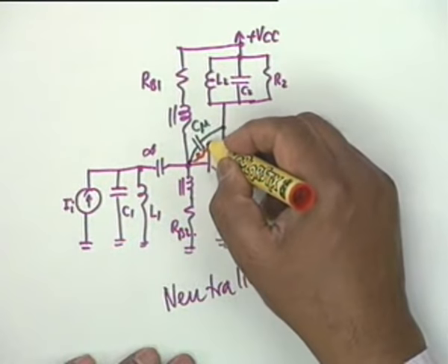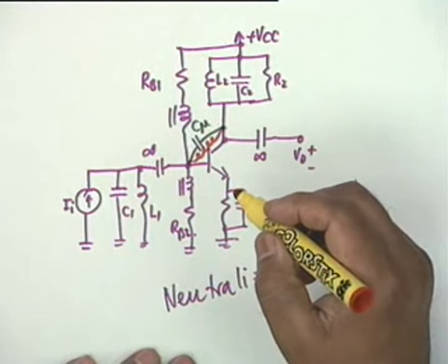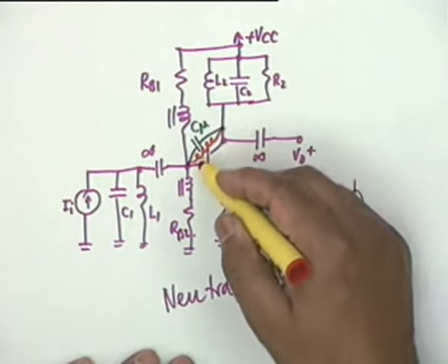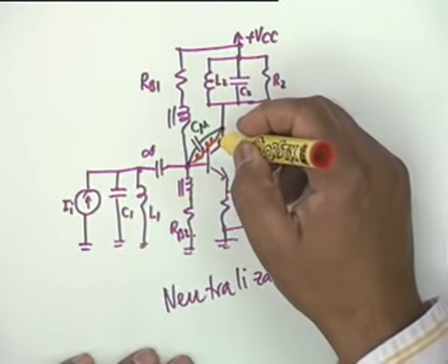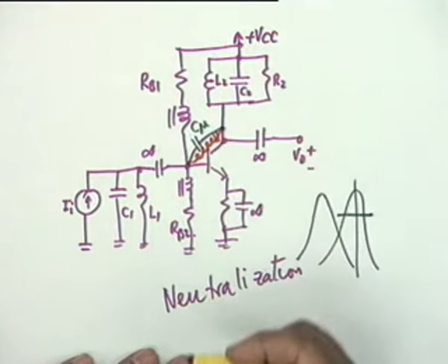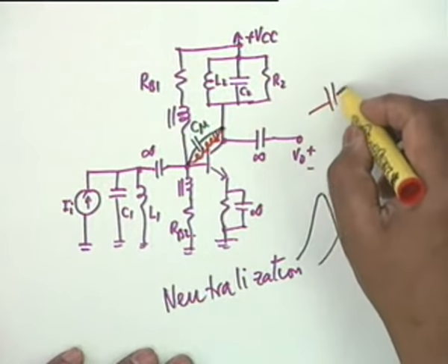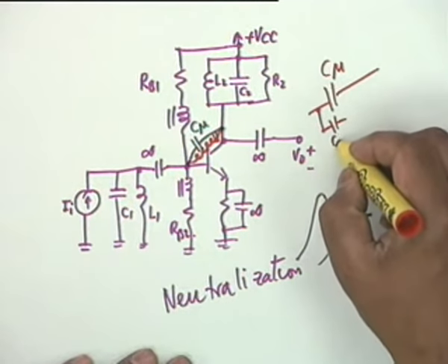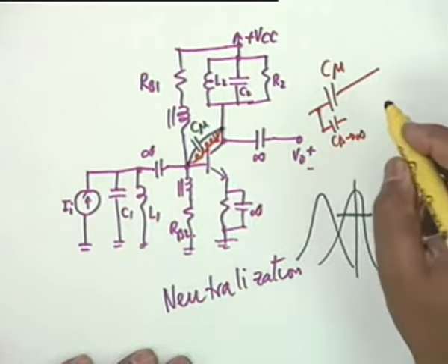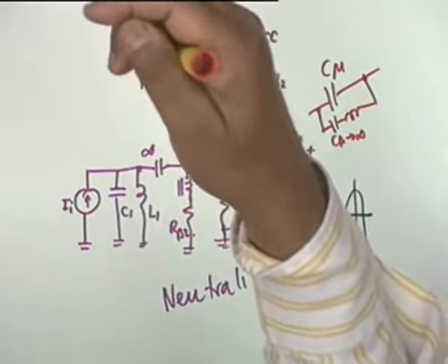Okay. One of the simple minded procedures is add an inductance in parallel. But you cannot add an inductance in parallel because the DC will go where? So, complication. You have to use a blocking capacitor here. You see, C mu, if you want to neutralize its effect, you have to have a CB which is very large, then an inductor, a small inductor, and at 100 megahertz, a piece of wire would do. A straight piece of wire has an inductance. That would do. So making this inductance is not a problem.